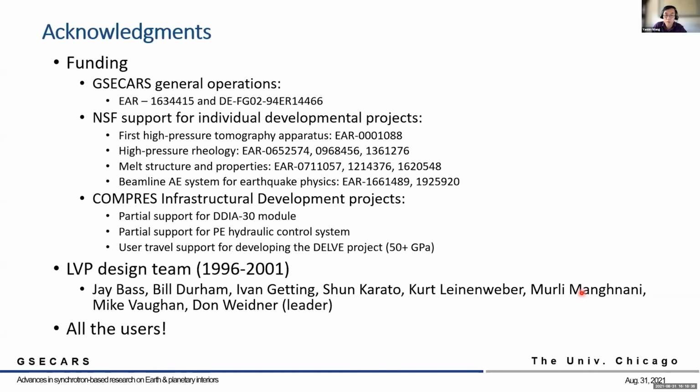That's a super good question. Thank you, Guillaume, for that. I actually forgot to mention that. So during the developmental time, it took roughly an hour to collect the data. Now it's down to about 30 minutes, somewhere between 10 minutes and 30 minutes, to collect quite a reasonable spectrum for the melt using the monochromatic diffraction.